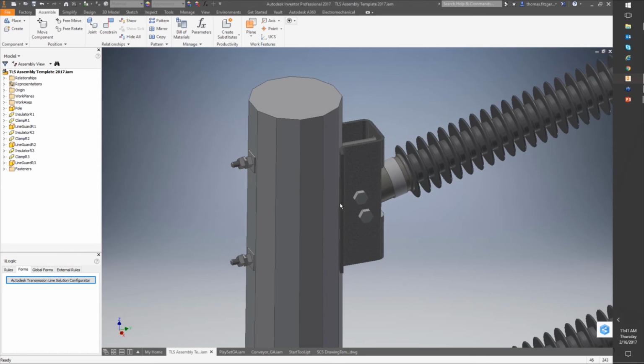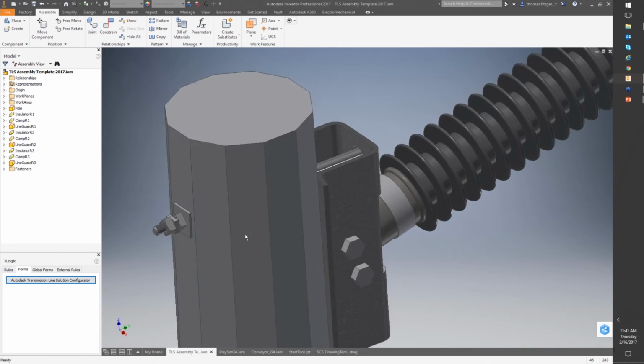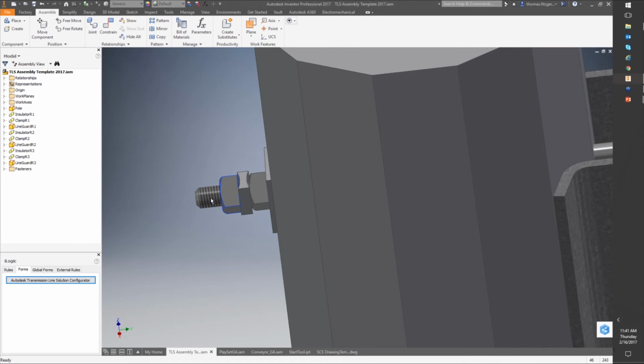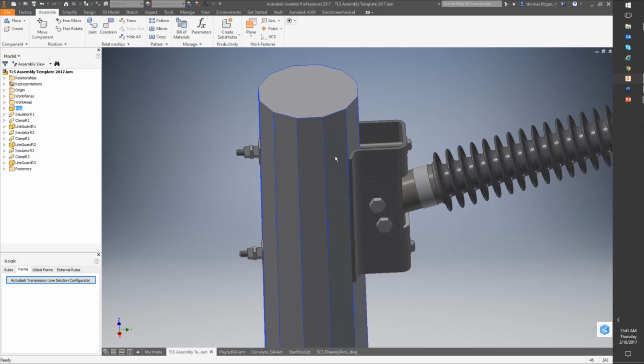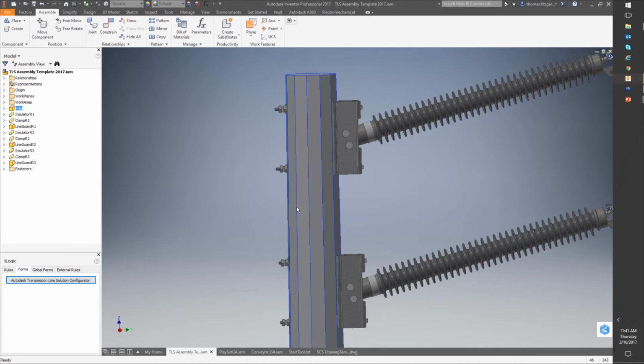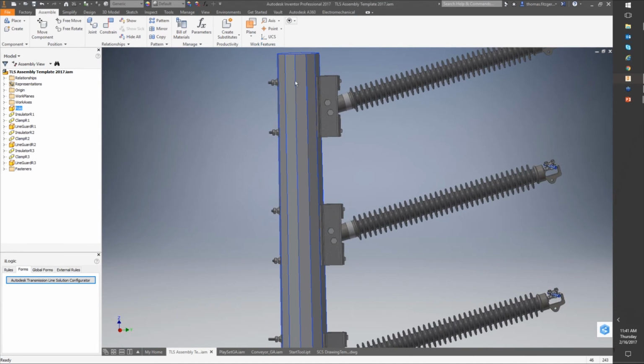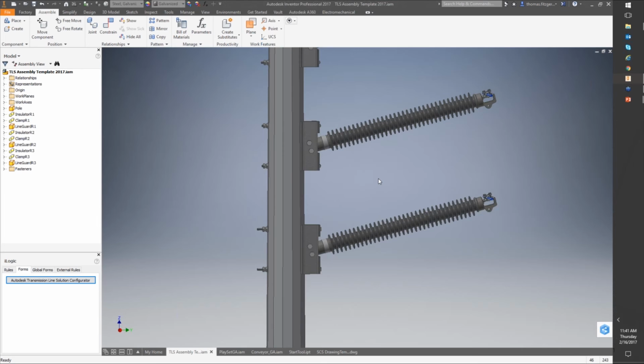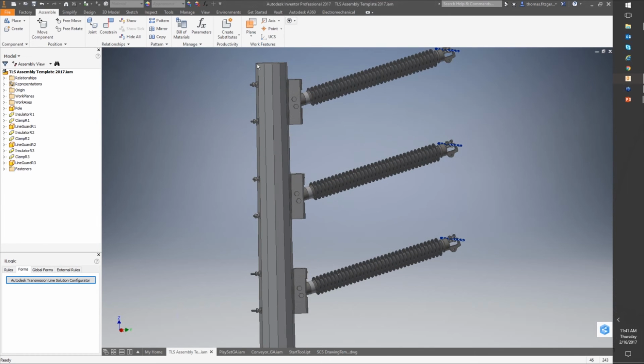If you look here at how I did these bolts, none of these bolts interfere with one another. This pole, as a matter of fact, is a tapered pole. So the diameter of the pole where this bolt goes through and where this bolt goes through is entirely different. I actually had to put in logic that did a measurement based upon where these bolts are going to be, and then peruse through the data source to find the appropriate length bolt.